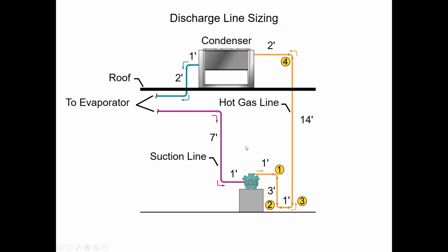Now, this is what was called a commercial triple split. What we don't see is the evaporator over here, but we had just a compressor unit. Typically, it was in the basement, and we did come out and we did do a regular trap on these years ago. We didn't want to come out and go straight up because we didn't want any kind of refrigerant, or I should say any oil, coming back and sitting on top of the head and waiting for the compressor to start.